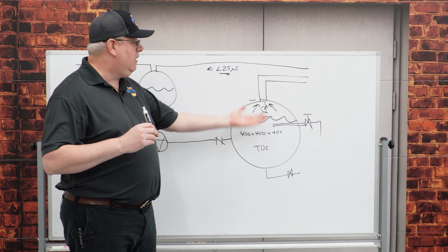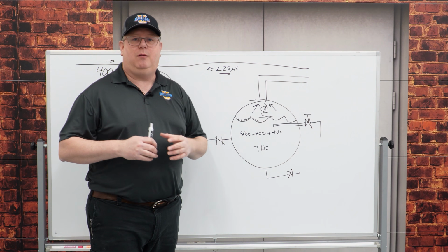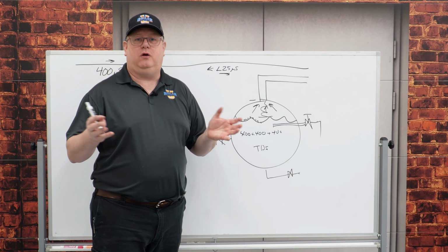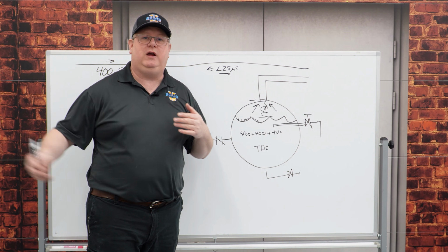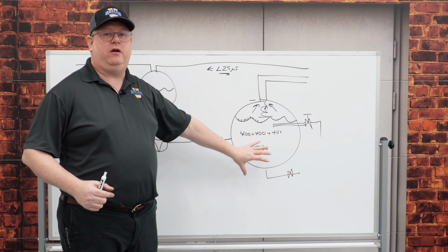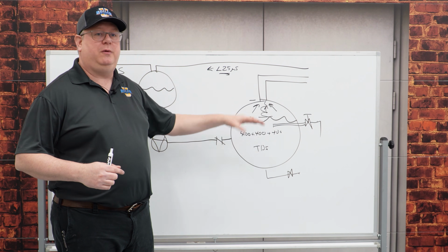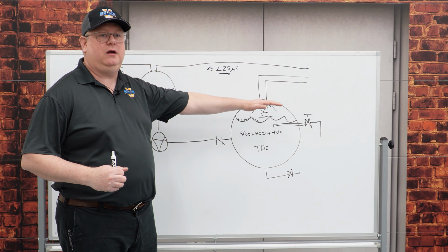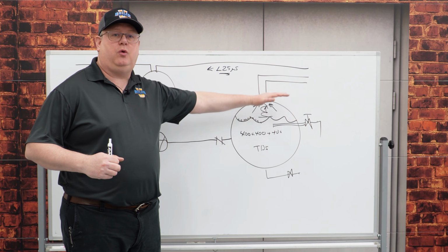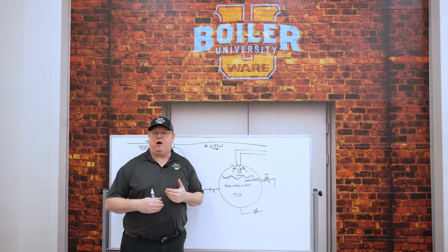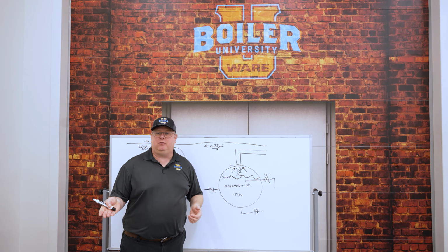But I do have a policy on high conductivity: if in doubt, blow it out. You know, it's going to be a short-term loss of energy when we skim or blow down aggressively, but ultimately we need the boiler to stay online. It's not unusual to get extreme fluctuations in your water level and have low water trips if conductivity goes beyond our limits.